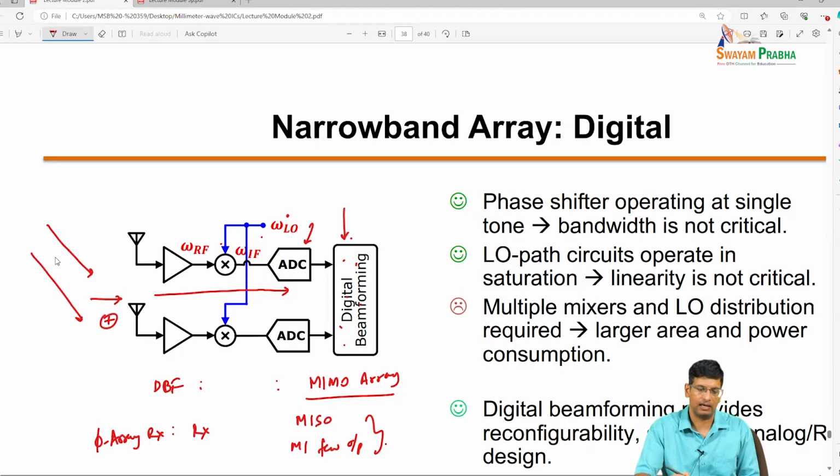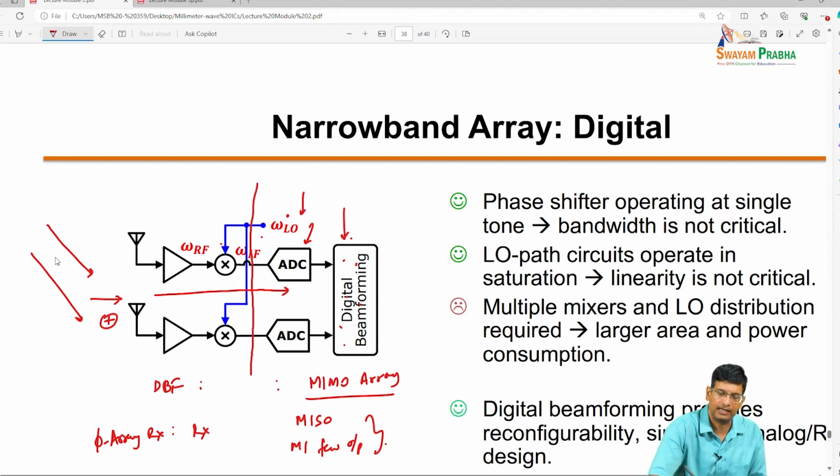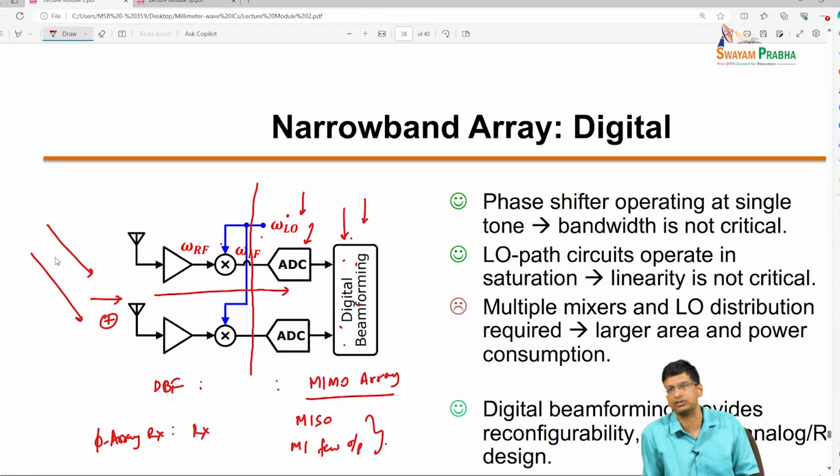So what is happening is that you're getting this sort of partition where the ADCs and DACs and the digital beamformers are being implemented in advanced technology, digital technology nodes, while you have signal chains that are being implemented in RF compatible technology nodes, and then we have digital beamforming arrays. So this is the way your FR1 base stations work, right? And going forward, there is a lot of desire to make millimeter wave work like this as well.